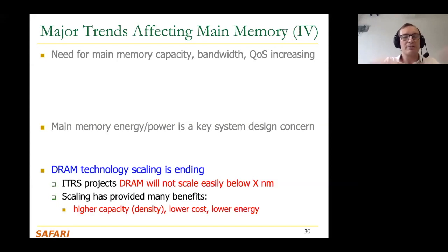Okay, so this is a more general treatment of scaling. But in terms of DRAM, the scaling is ending because people are a lot more worried. DRAM has reached its limits because of the capacitor much faster than transistors themselves. The capacitor is much harder to scale because it's a much more leaky structure actually. And we will discuss this a lot more as we go along.